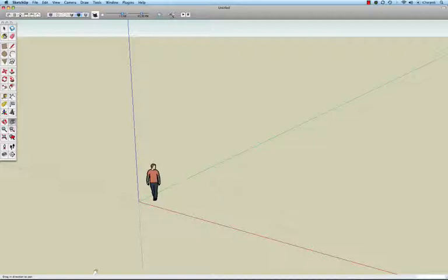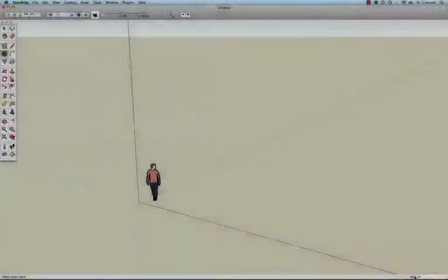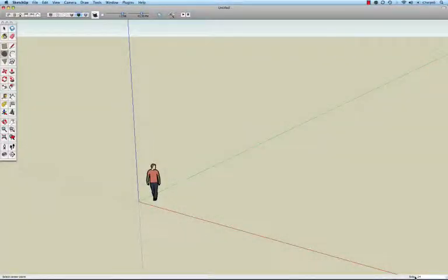Along the bottom left, you'll see the status line, like in Photoshop. Depending on the tool selected, the information will be unique to that tool. For instance, if I choose the circle tool, it will ask you to select the center point. Along the right hand side is the VCB, the value control box. Basically, it's a box to type in numbers in. For example, you can type in how many sides the circle has. We'll worry about that at another time.